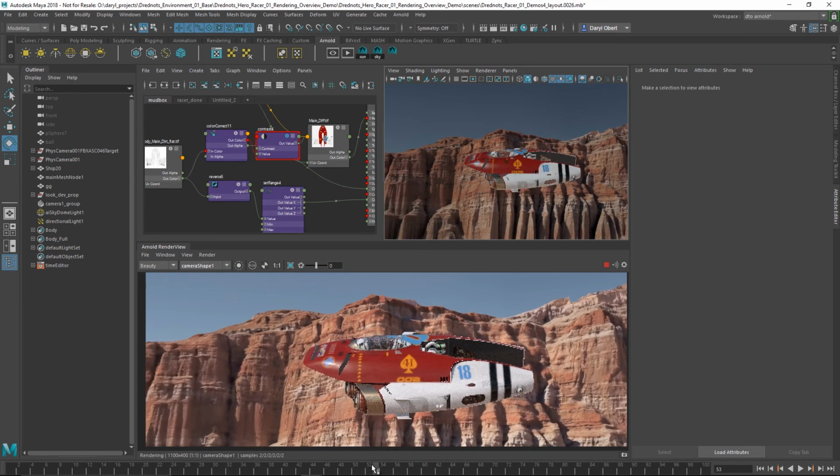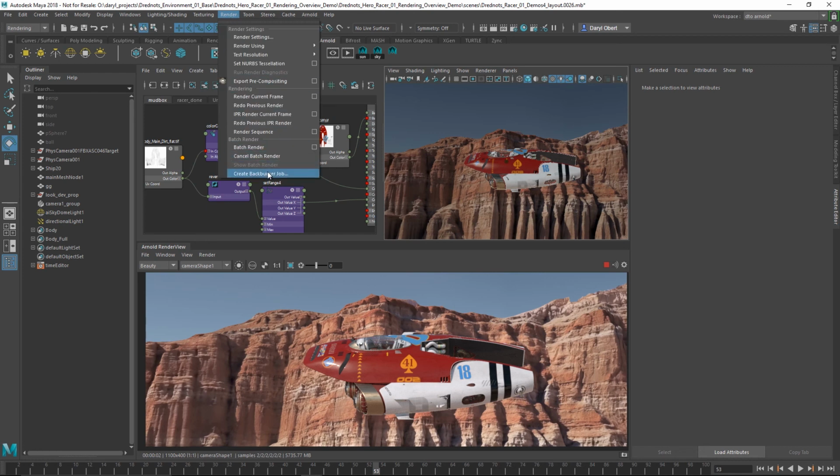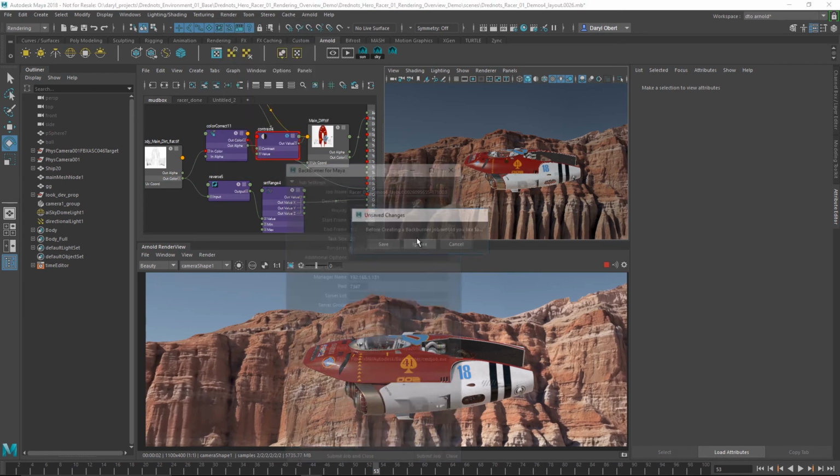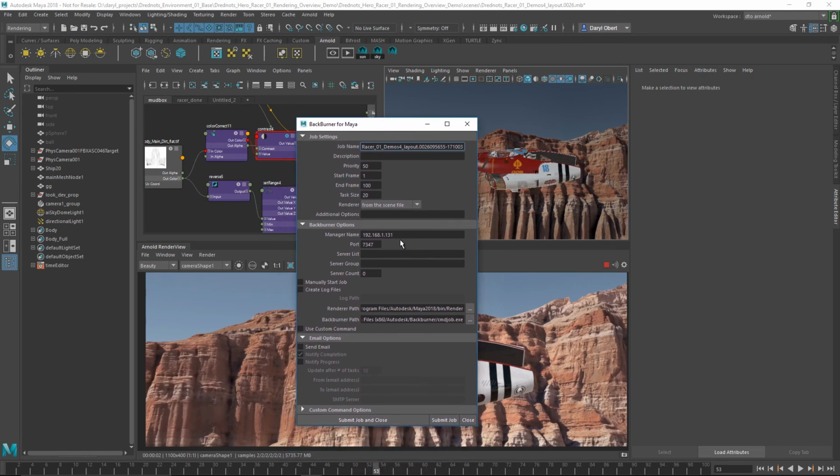The next thing that we want to do is launch this off as a batch process to render using that Arnold 5-pack. This is pretty cool. We're going to jump over to our rendering menu, go into the rendering setup, and I can basically start a background job using Backburner. What this is going to do is go through and find all the render nodes that I have on my local network. It's worth mentioning that the collection also has the ability to render both on your local network and on cloud. You have cloud rights with the M&E collection. We're going to be using this background renderer to utilize all the assets that I have in my facility. So we'll go ahead and submit the job.